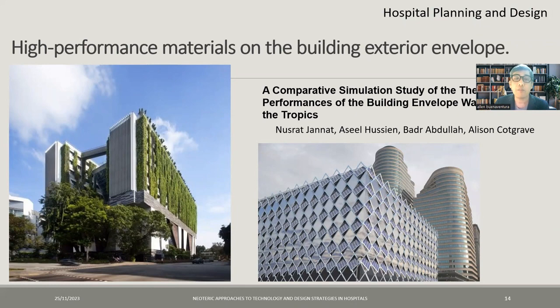The thermal mass improved with increased thickness, which also resulted in better thermal efficiency. The energy consumption of spaces significantly varied depending on the shape of the spaces. The spatial orientation influenced the thermal performance of the external wall, as the maximum surface area exposed to solar radiation causes heat gain. The best performance for tropical climate conditions was obtained for buildings having the elongated surface oriented north-south.